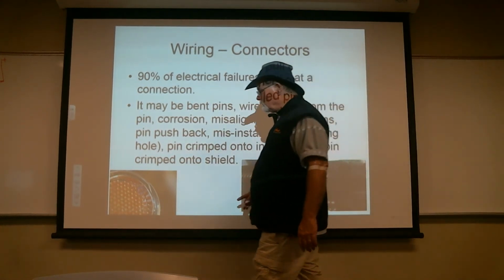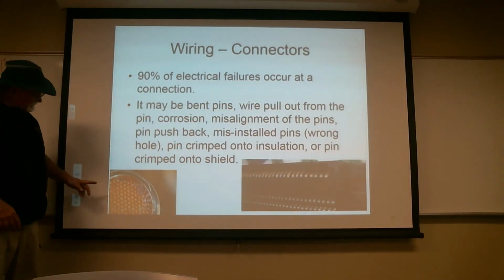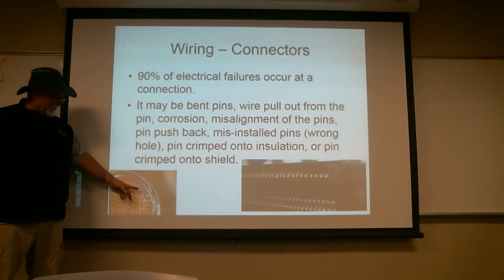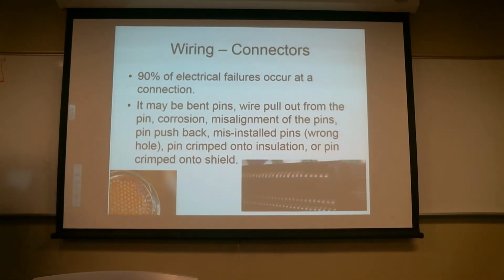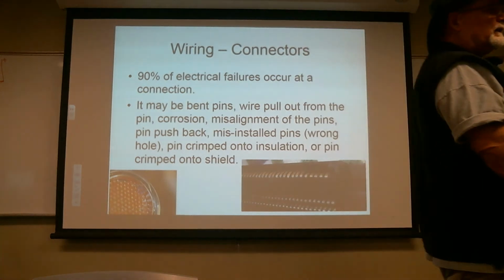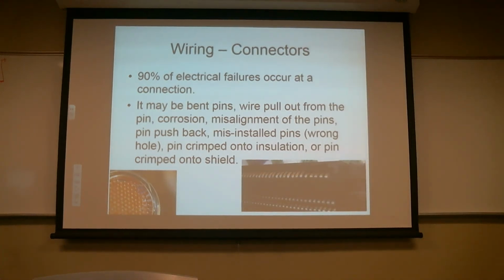Now this one, it's a little hard to see, but it's actually also got a misaligned pin. This pin right here is bent over some. In all likelihood, that connector may work depending on how the female side of the pin is set up. Instead of going in the hole, it may go there and sit on top. Pin misalignment. Of course, when it does that, what's it going to do? Intermittent. It's going to work just fine until it gets nice and far away from you, the mechanic. And then it's going to stop working, and the customer is going to freak out. The first thing they're going to do is say, I got ripped off.